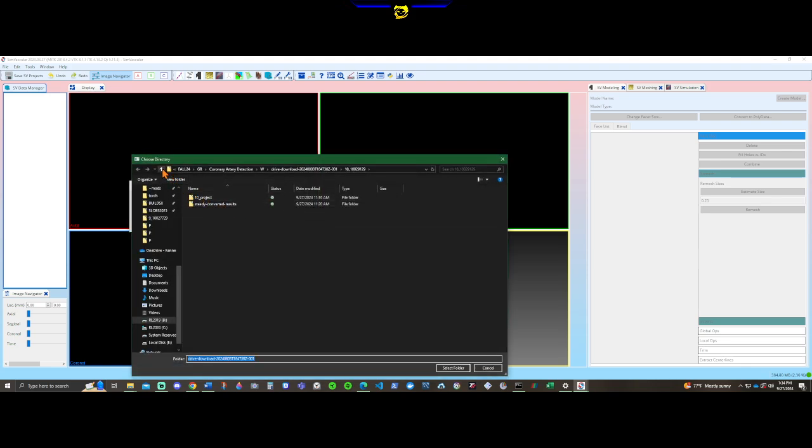I think you can have it all under one SV project, and as a matter of fact, I think that way would be even better. That way you can have multiple simulations, and you don't have to keep writing the parameters for the solver, which we'll get into later. So this is just to have the STL files.